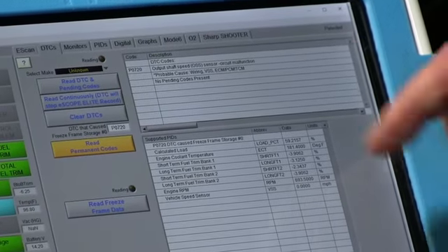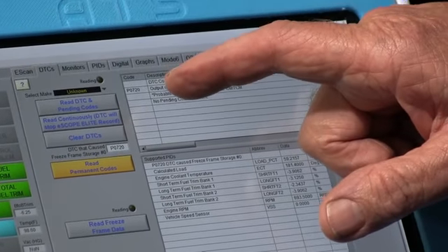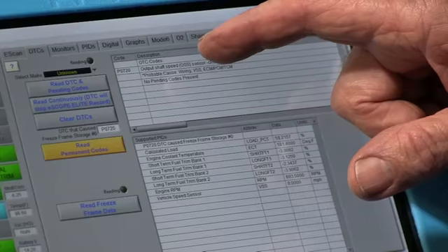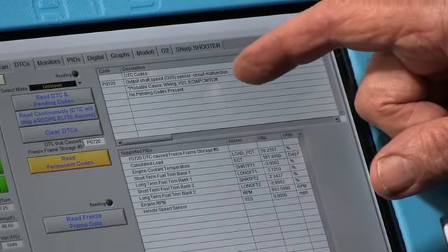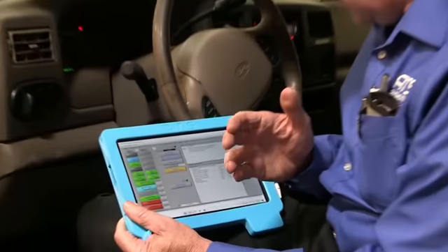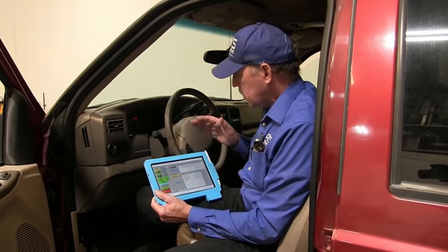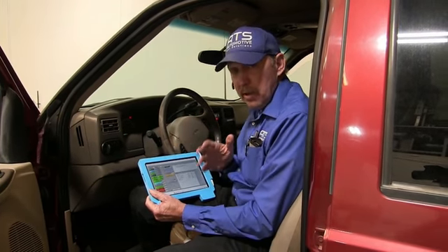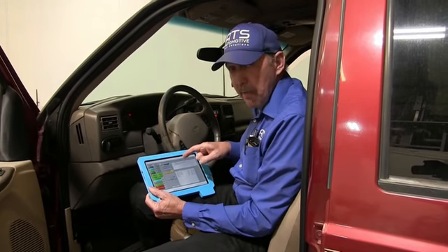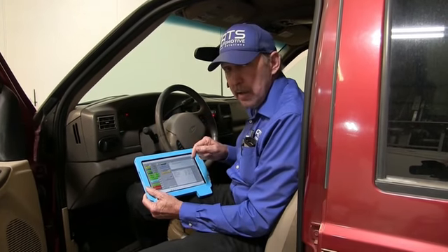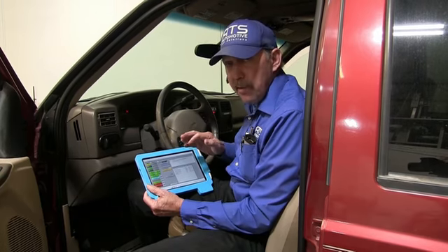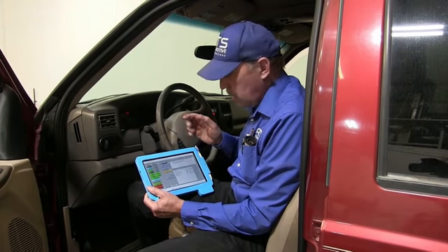Okay guys, so we got a code for the transmission output speed shaft sensor signal. Now right now you would say, oh, how can that speed sensor cause this car to die? But let me tell you, you better be worried about that code for this car stalling. You know, most people would look at that and blow it off, like, where's my crank code?